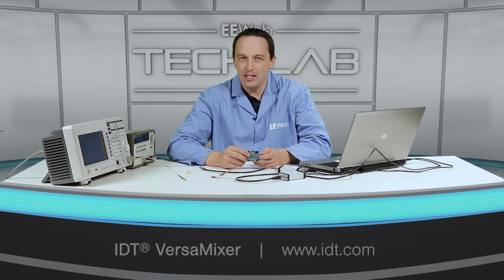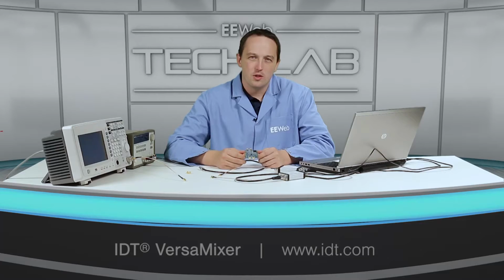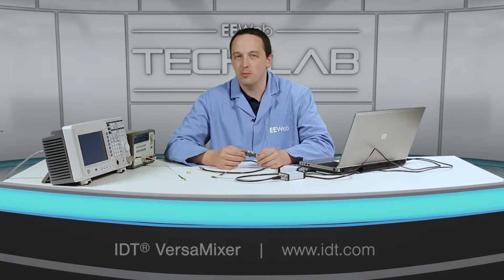The mixers feature IDT's flat noise and zero distortion technology. Flat noise keeps the noise figure virtually unchanged as gain is reduced from its maximum setting, giving designers more flexibility by providing the best SNR possible. Zero distortion reduces third-order intermodulation distortion by approximately 90% to improve coverage, quality of service, and spectrum usage.